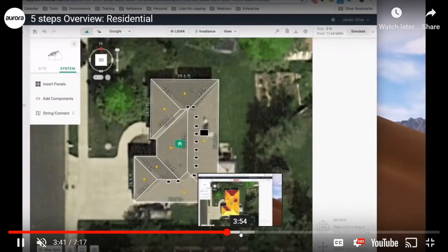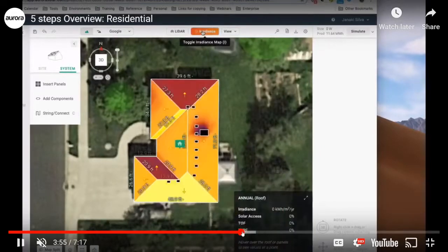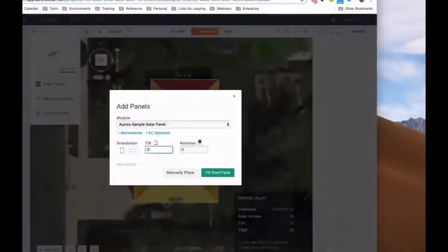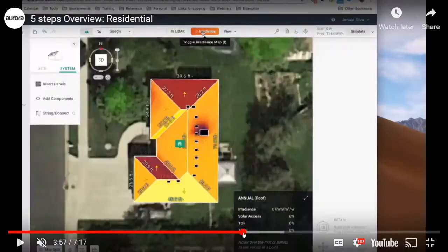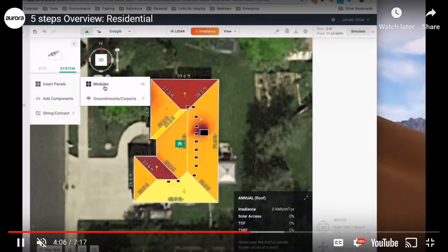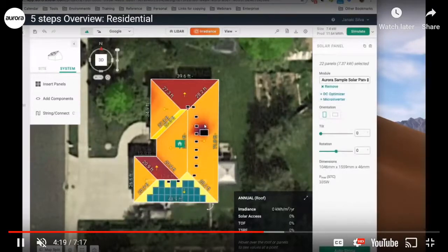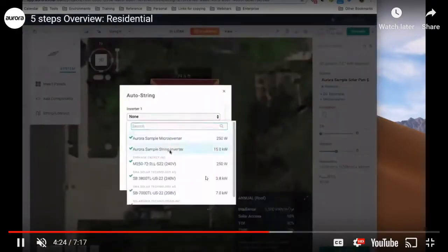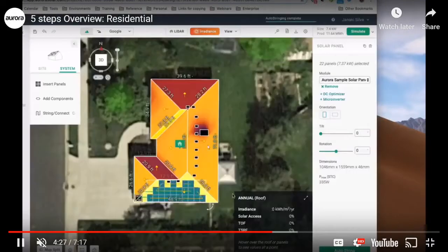And then here they're drawing obstructions. And so now they're doing a shade analysis. And so obviously the south side works well, and the north side is the least sunny. But we can also note just how large this area around the chimney is, and so we can say, okay, if I stay out of this area, maybe I just want one array surface, or knowing that I'm going to have a broken array surface if I go into this larger area.